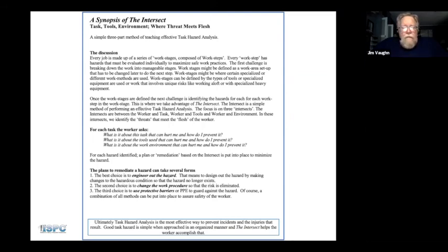We were building a 500 line for a Salt River project, and they were using a new vendor manufacturer for poles and arms. And as they were hanging the arms, they started noticing visible cracks in the welds where the flange on the arm was bolted to the pole. So it turned out that they came up with a repair, and we call it a Band-Aid. It was 80-pound sleeves that slipped over the arm, bolted to the pole, bolted to the arm to give a reinforcing backing.